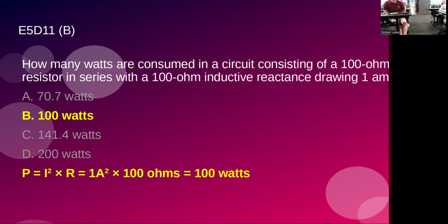Let's see. Yeah, 1 squared times 100 is 100. Not two. Maybe because of the series, you were thinking add 100 to 100? Sure. It asks for how many watts are consumed, so it would have to be real power. So the reactive part of it doesn't matter.